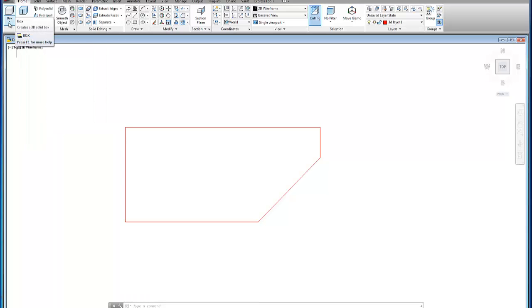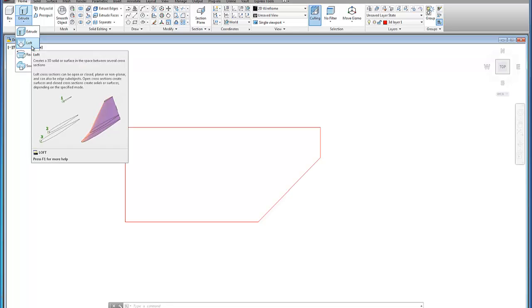Now there's also pre-made objects that you can use: boxes, cylinders, cones, spheres. So within the 3D modeling environment, I can have core components created. I can extrude, loft, and a loft is basically taking two differing shapes and saying between the 2 differing shapes, or the 3 differing shapes as the little pop-up shows, I can make a smooth contour.